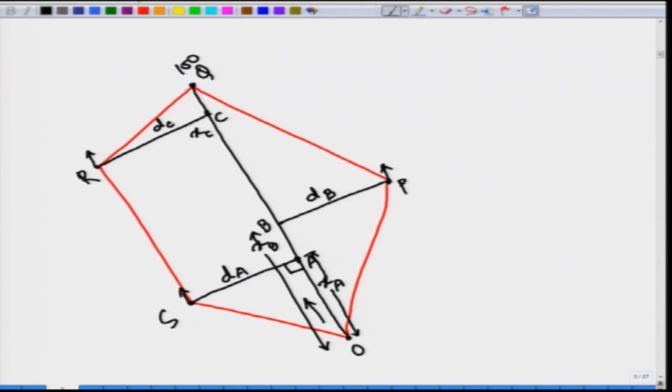Now, in this case you are only taking the linear measurements, you are not taking any angular measurement. You just go to a point where the next point is either completely to your right or completely to your left, and you are then measuring where you are standing, and you are measuring the distance of your stakes from this point, either to the right or to the left.